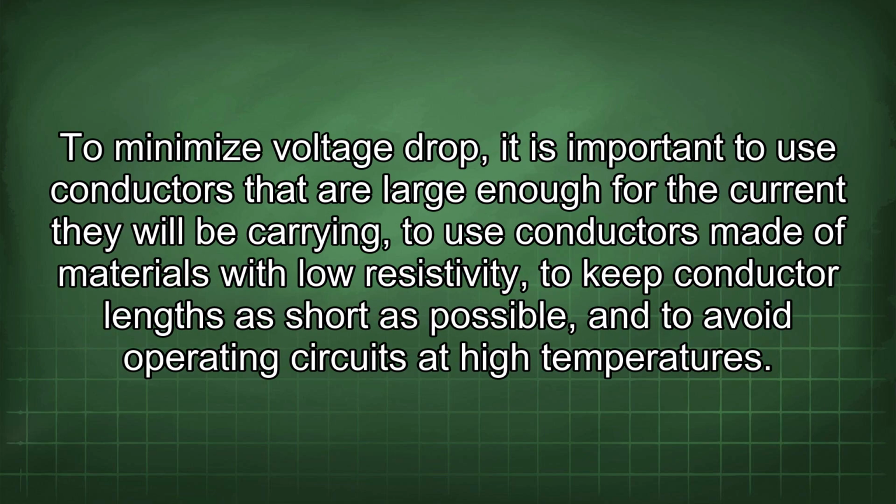To minimize voltage drop, it is important to use conductors that are large enough for the current they will be carrying, to use conductors made of materials with low resistivity, to keep conductor lengths as short as possible, and to avoid operating circuits at high temperatures.